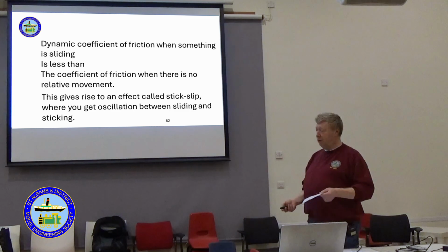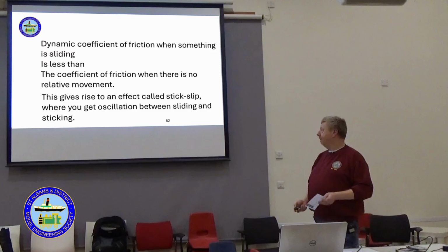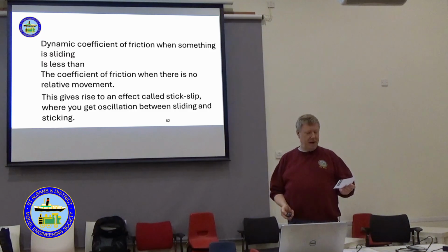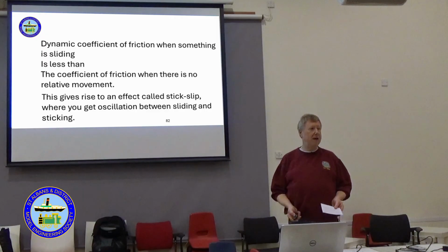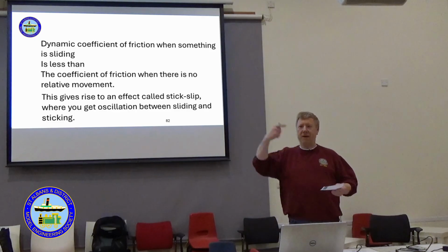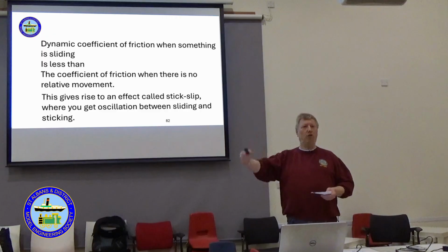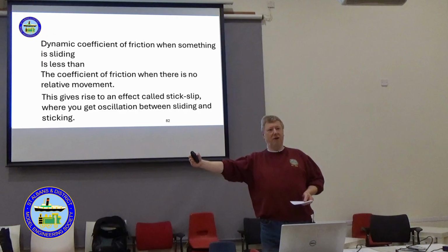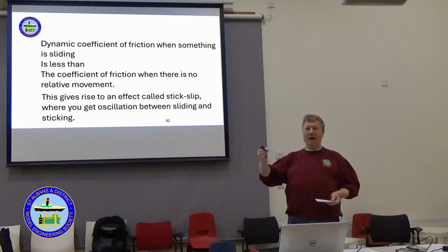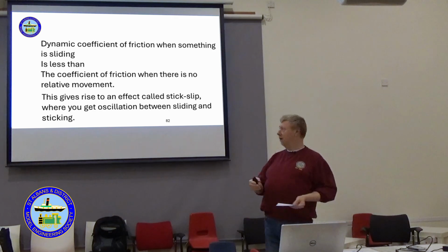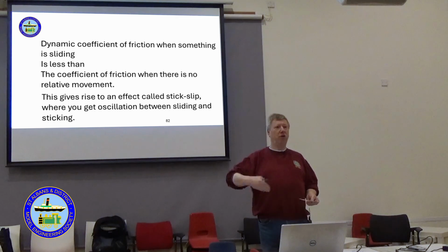Now obviously in a locomotive, it's not necessarily very desirable. It can lead to corrugations in the rail. It's a notorious problem that used to happen with steam locomotives, where the traction was varying as it goes round in its cycle. It's not constant on a steam loco. If you think about it, when the piston's at one end, you're creating no traction at all until it starts moving back the other way, and then it goes back to zero again. So you're constantly oscillating the traction. With modern traction motors, it's constant.